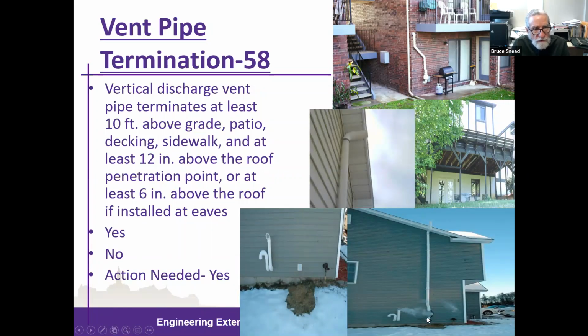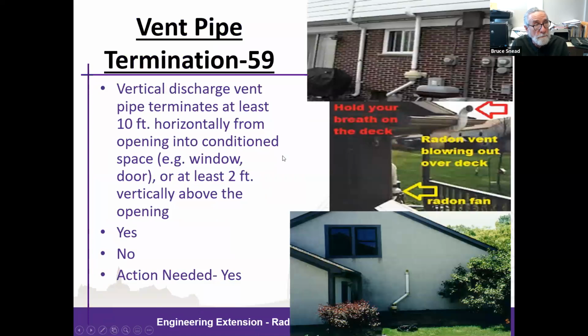And then after the system was inspected and this defect identified, the new radon vent pipe, which runs up the outside wall and vents above the roof. And improper locations up in the upper portion here, too close to occupiable spaces outdoors. Again, further distance requirements for location of the vent pipe.